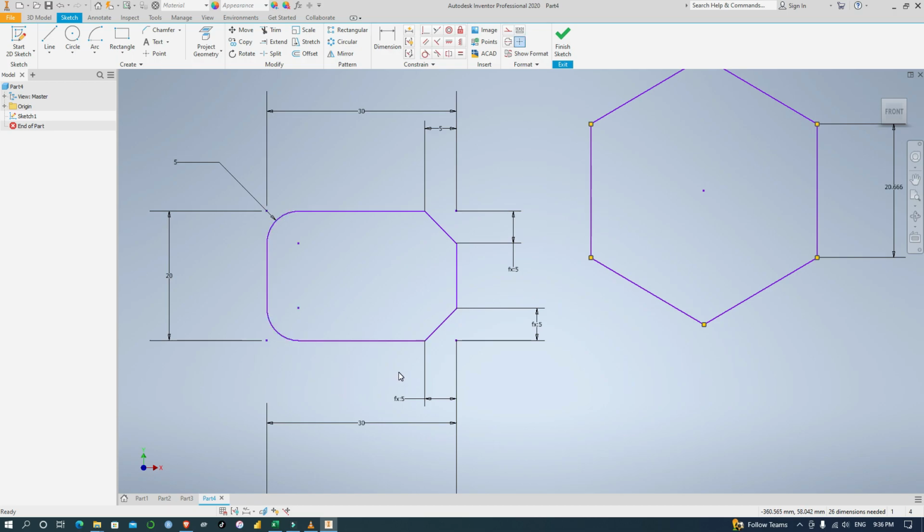However, if I move from right to left and highlight these, it will highlight any point that has been touched. For example, now you realize that it has selected all this from here all the way to this, because using right to left, it selects all the points where the selection points are marked. However, moving from left to right, it selects only the points that have been fully highlighted. So that is the difference.